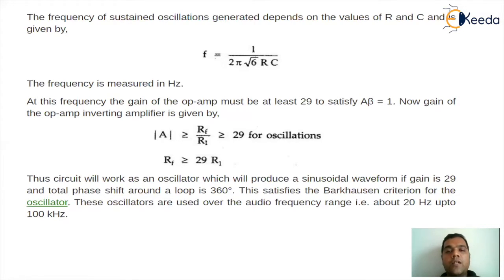A small conclusion regarding RC oscillator and RC phase shift oscillator. RC phase shift oscillator using op-amp is utilizing 3 RC networks, whereas an RC oscillator circuitry using the concept of Wien-Bridge is using a combination of RC series and RC shunt. Both the logics are completely different because in both the cases, the type of amplifier that we are using is completely different. So we have to be very careful with the equations and the pattern that we use to get the waveform properly.